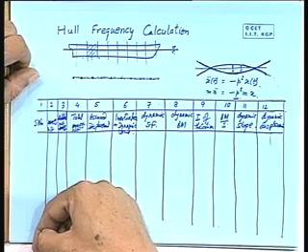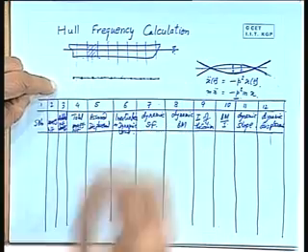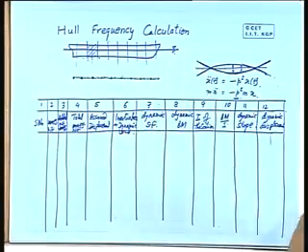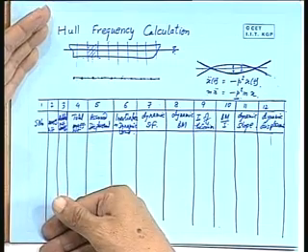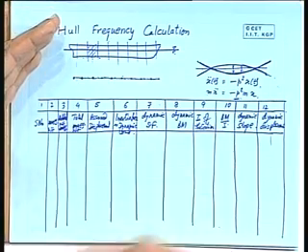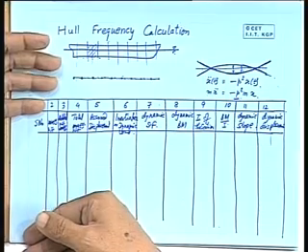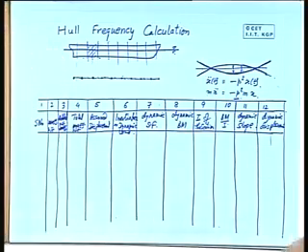So actually what we are trying to do here is, the number of stations which we take is the number of masses we are considering. And that is what I was saying, that it is basically a multi-degree freedom system, and depending on your computing capabilities, if you are doing it physically, maybe we will take only 11 masses here, as we do for the line spline. But if you have a PC available and somebody to feed in the data, then why this much? We can take actually at every actual frame space, because all those data is available with you, right?